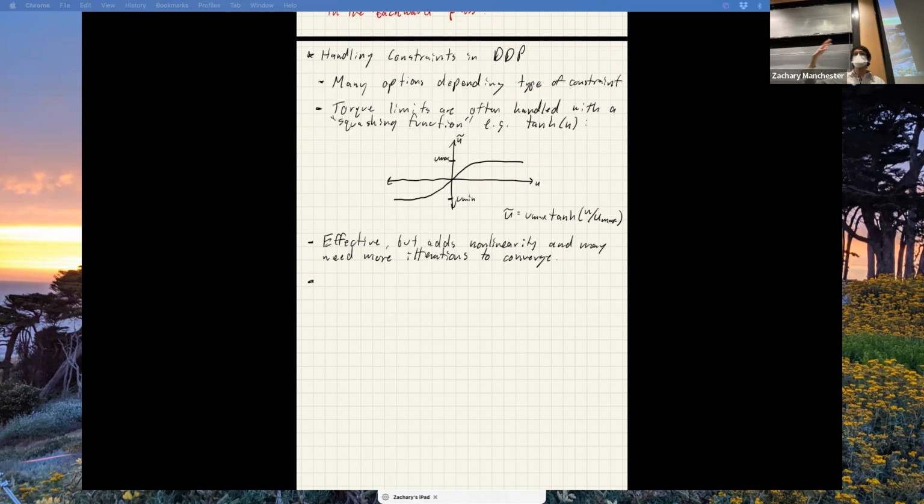I can actually just, instead of that unconstrained solve, solve a constrained QP at each time step going backwards with the explicit constraints in there. So that's sometimes called control limited DDP. So when I solve for delta U, it's going to be argmin over delta U of my action value thing.